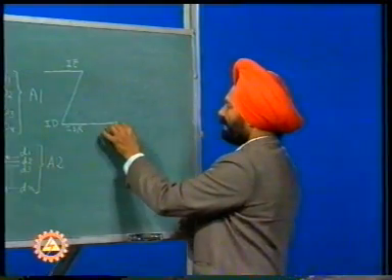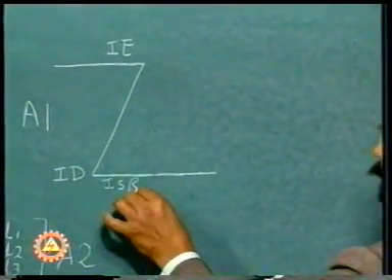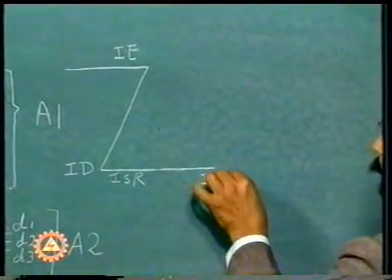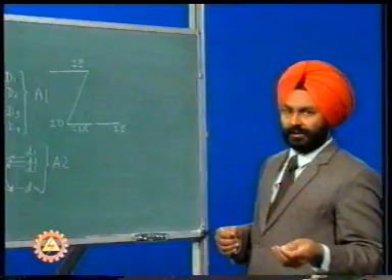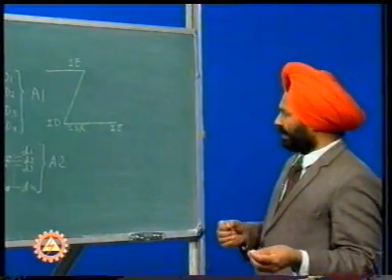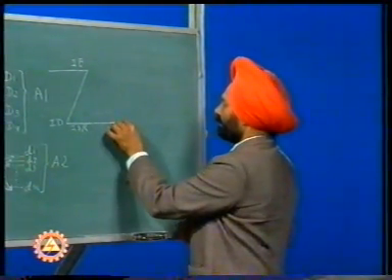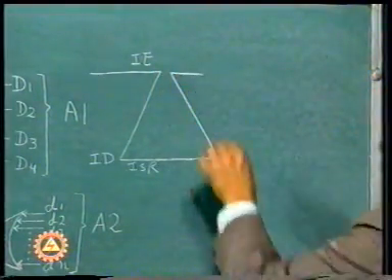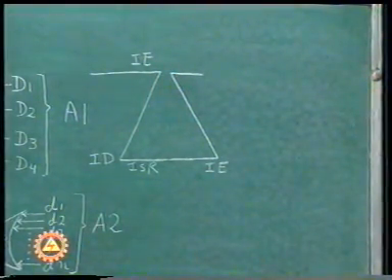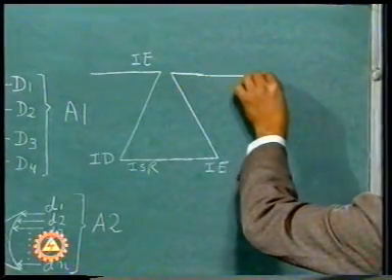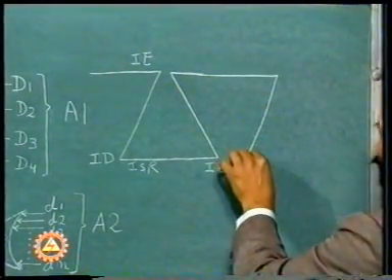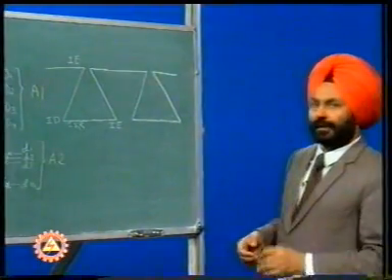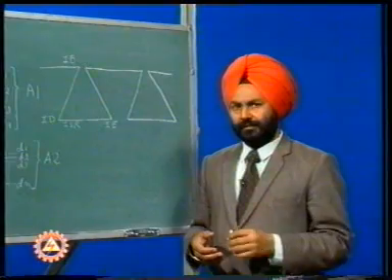Then near the end of the servicing of the interrupt service routine, the interrupt system of the microprocessor is again enabled by execution of some instruction like enable interrupts. Then the microprocessor goes back to take up the execution of the routine program. Again, if any other interrupt happens to come, that will be serviced accordingly. This process goes on. But there can be a changed situation.